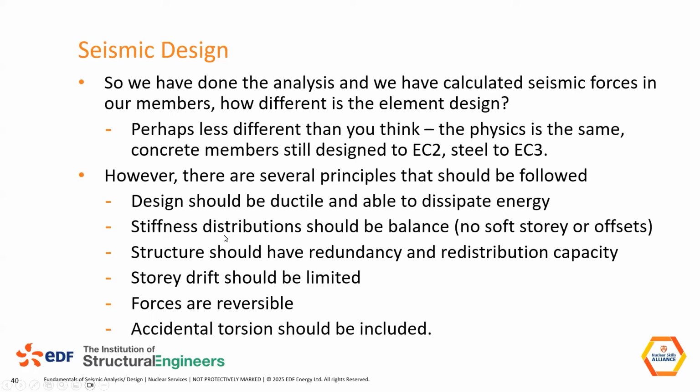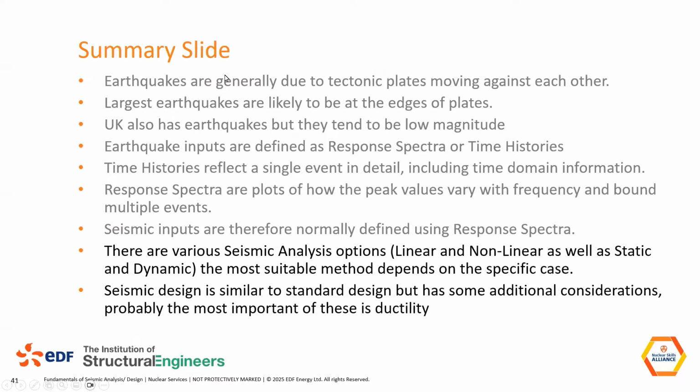I think the main thing is the actual design of the elements: you're basically going back to Eurocode 2, Eurocode 3, Eurocode 5 for timber. It's the same engineering, the same principles. I've noted a couple of other things here, but due to time, I'm just going to skip them. So, going back to our summary: there are various seismic analysis options, and the most suitable method depends on the case. For design, it's actually quite similar to standard design, but we really need to consider ductility in particular.